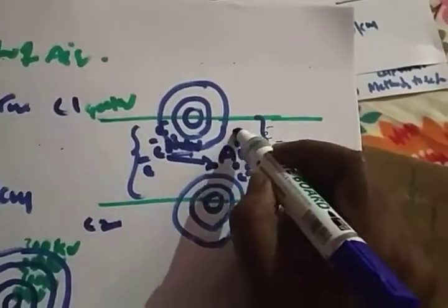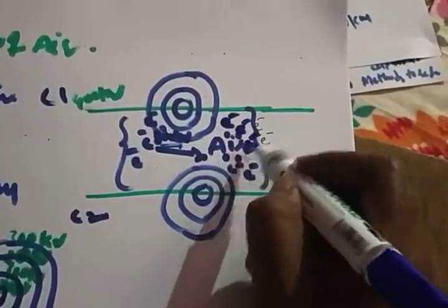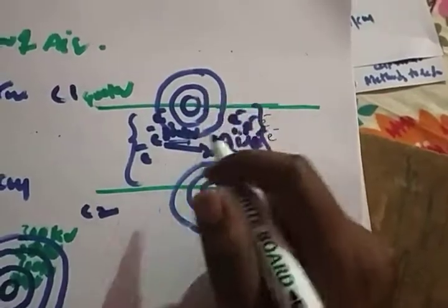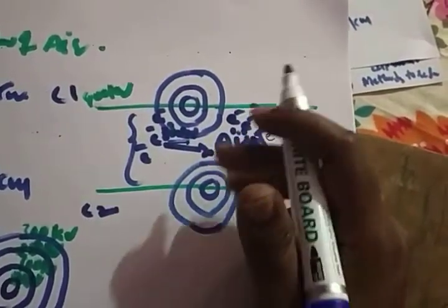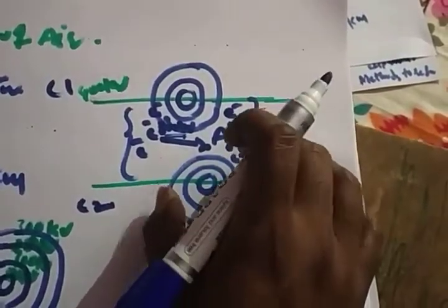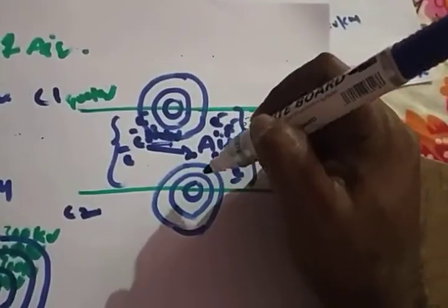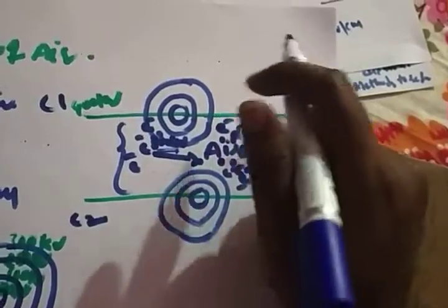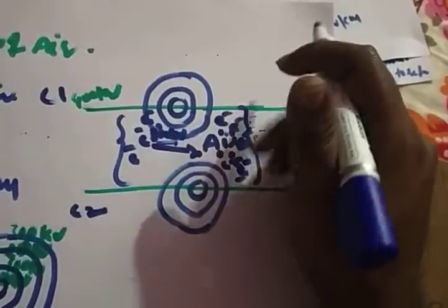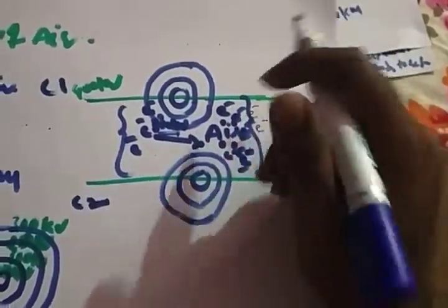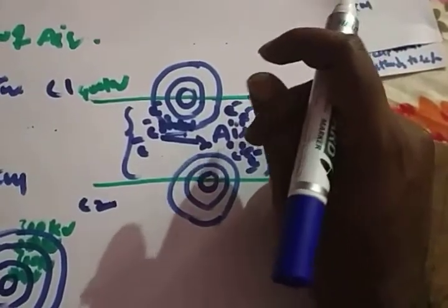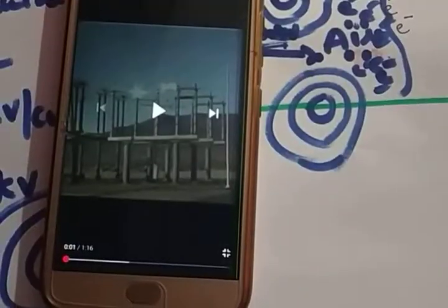It's like this, all the place will fill with electrons. So when the space between the two conductors fills with electrons, it will make a conducting path from this to this. So some sort of hissing and violet glow will occur. This phenomenon we can call a corona.